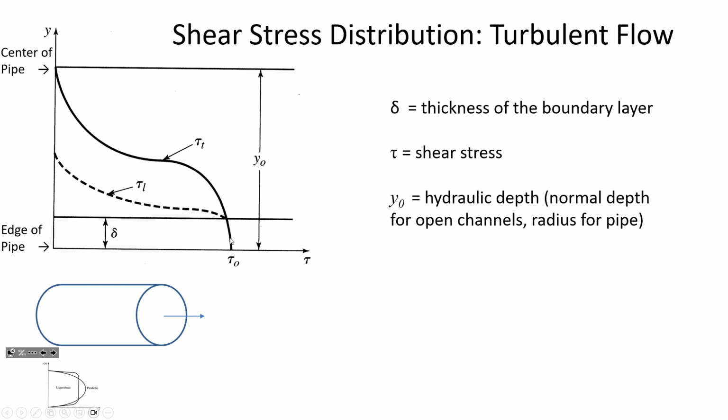In laminar conditions, when conditions are laminar, that means a slow-moving velocity, and this is just showing that the shear stress doesn't extend as far into the liquid when you've got laminar conditions, that the pipe isn't holding on to the flow as deeply into the pipe. It's just at the edge, maybe, that the pipe is extending its influence over the fluid.